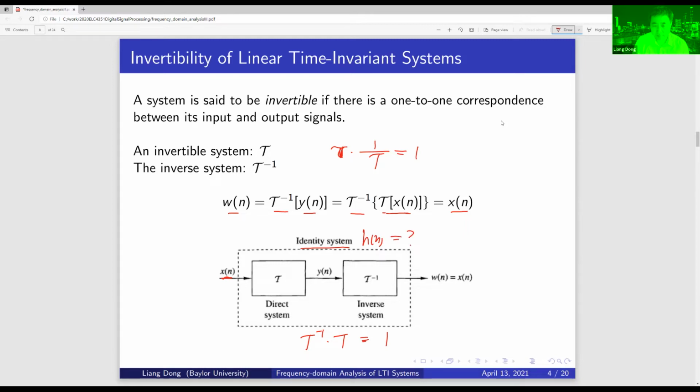For an identity system, that is quite straightforward. We do an inverse Fourier transform. What is the inverse Fourier transform of a constant, especially 1? That should be equal to delta n. Delta n is just a delta function. Indeed, xn, the input signal, convolved with a delta function gives me xn. So the output is still xn. Therefore, that is the identity system.